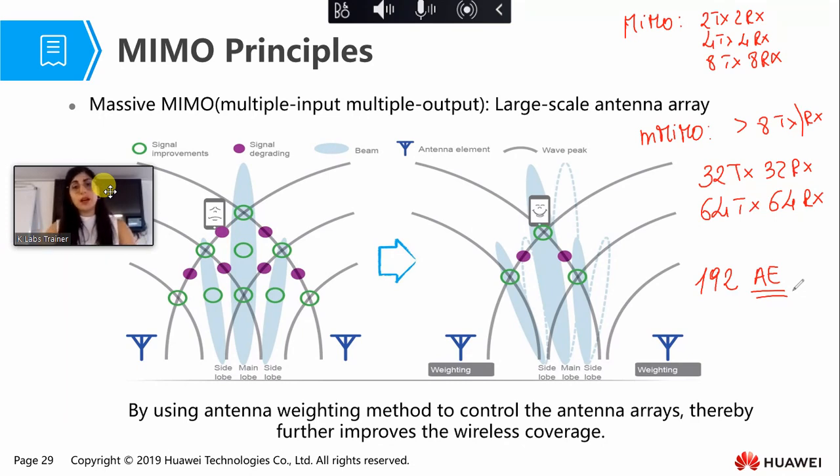And another advantage is that having many elements, we can give polarization to our antenna, and we can accomplish beam forming. What is beam forming? Basically, basing on the difference in phases of the feeding that we give to our antenna, we can weight our beams toward the user equipment.